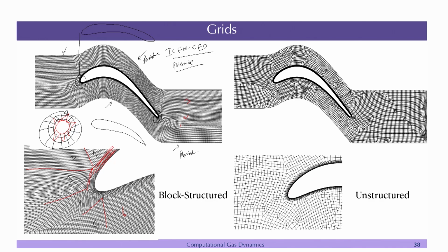You can see that there is a very nice boundary layer very close to the body. This is the boundary layer that you met. This is basically conforming to the geometry that we have. Maybe you have 20 layers or 30 layers of those boundary layers, but away from that, because the domain is very complicated, you can just fill in the unstructured elements.